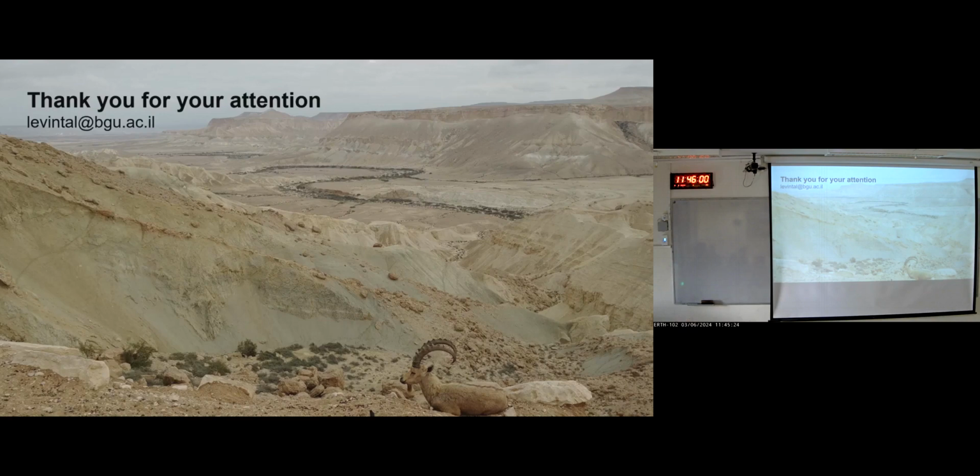Yeah. So I really like the talk. I like this approach. Something used in the past. I wonder if you can comment on 2 problems I encounter when trying to use this approach. One is when I'm using a few of these cheap sensors, they tend to drift and then have differences between them. So there's always the challenge of calibrating. Sometimes I use switching into air, calibrating, or some internal. Otherwise, I found I need to go every day or 2 to calibrate it.